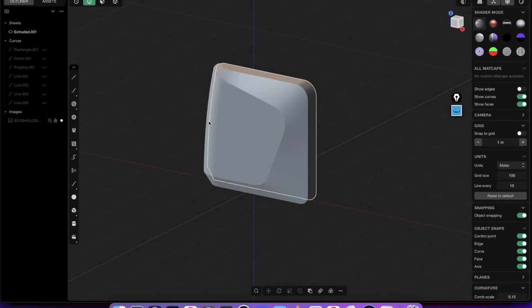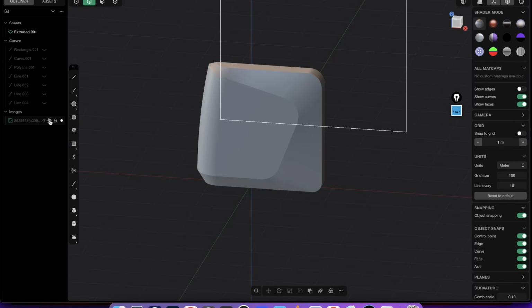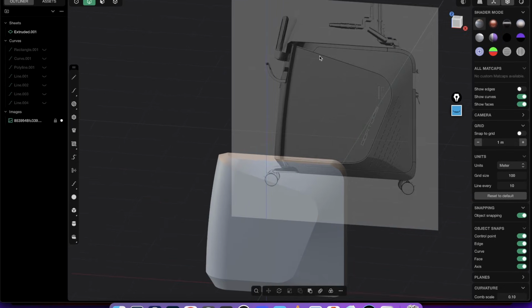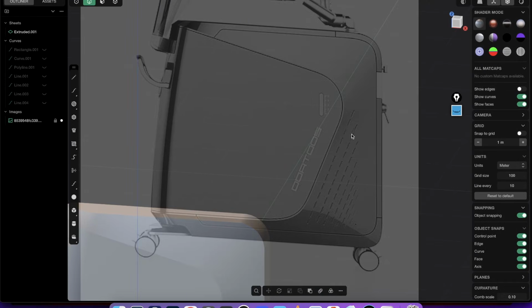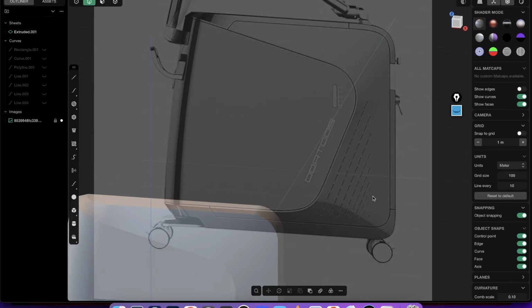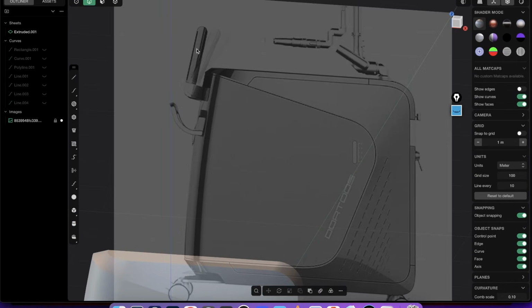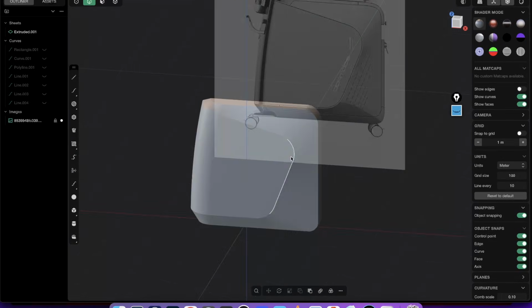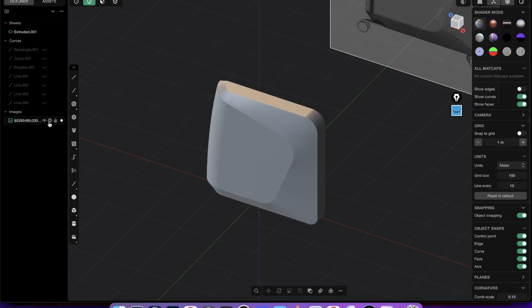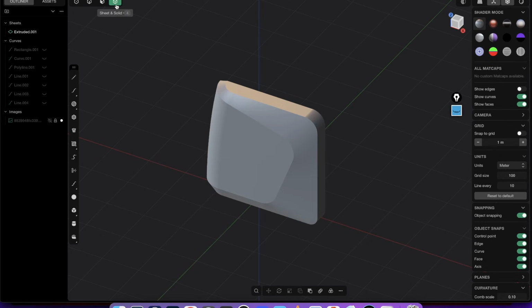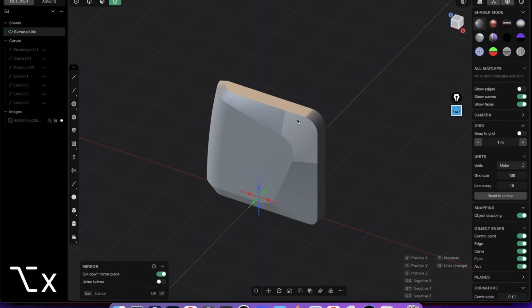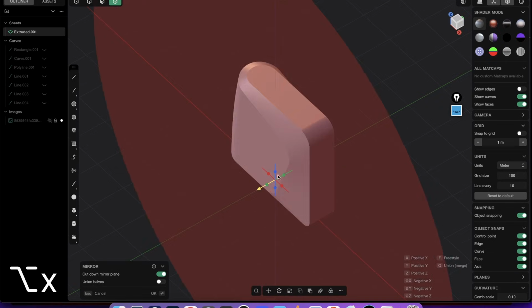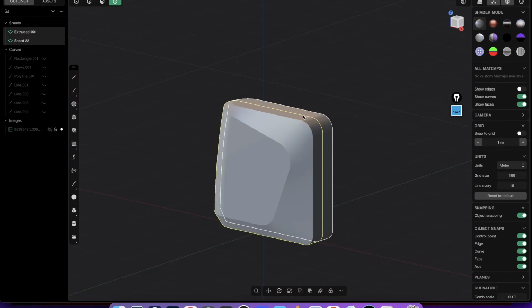And now we want just to add here some cuts. Right, so again, obviously you can add now all of the details, the rollies here and this other stuff if you like, and add all of the stuff, but I just want to show it to you with one example. So select object mode, select the surface, Alt X for mirror command, and bring it to the other side, right click, join that, make sure you have a solid.